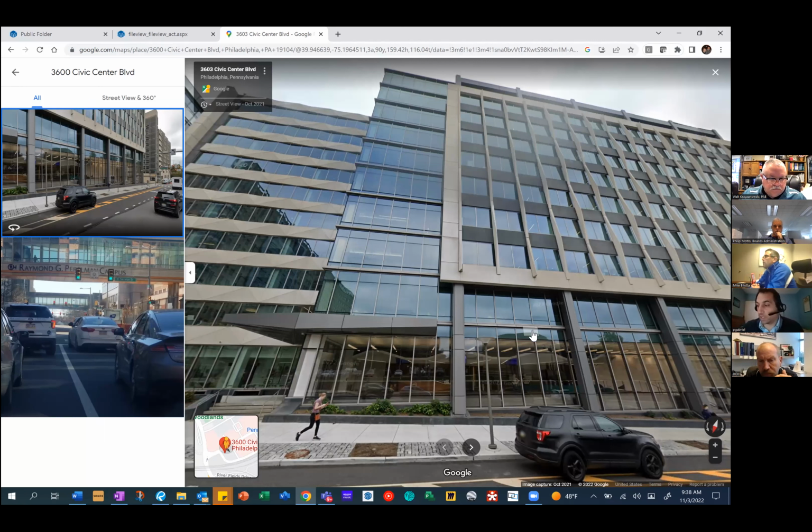The intent of the building construction, or the intent of the future building, is to add another 8 stories on top of this, all lab space. So again, we're modifying the existing building. The existing building has a green roof on top. We'll get into some of those details a little bit, but I want to provide context. Zoning has been approved, so we're on the path forward through the construction process. The nature of this appeal is to specifically change or to not have to modify the interior part of the building as it relates to the storm riser. Currently, it's one storm riser that goes down, multiple roof drains, and there's a scupper system.